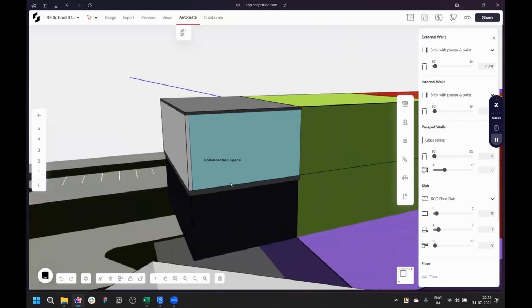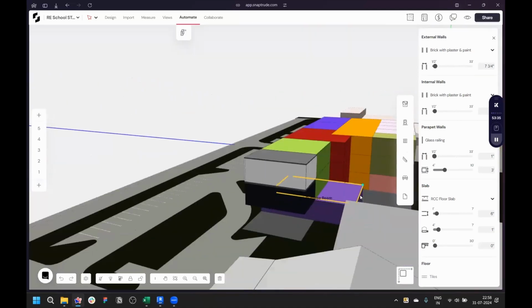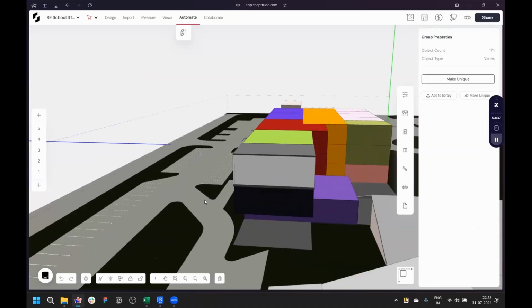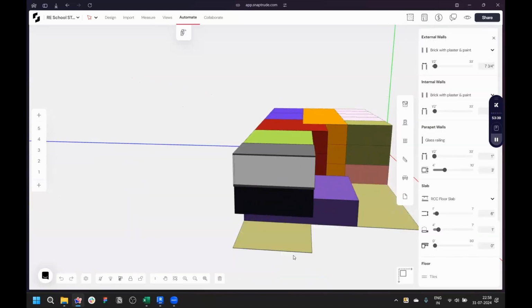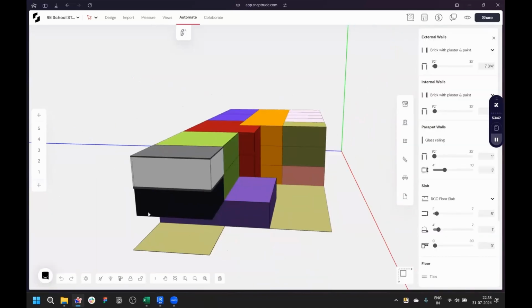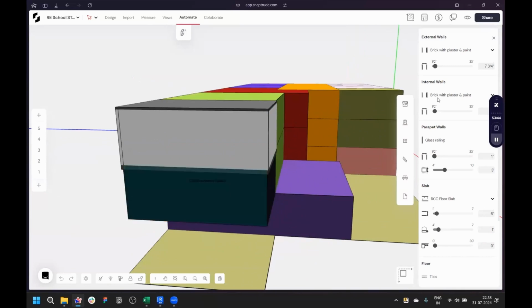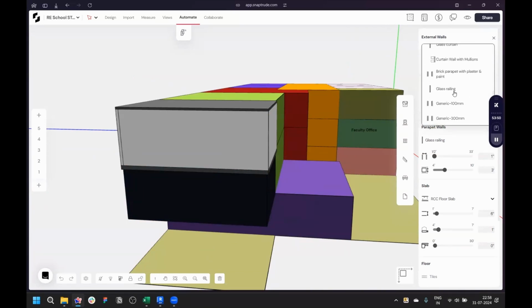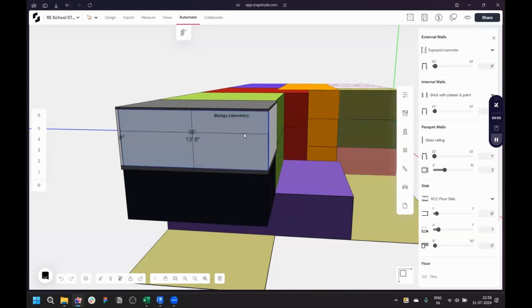And a couple of things. First of all, the person in the chat asked about exterior, what type of walls? This is what I was referring to. In our create building functionality, you can choose the type of wall, and it's actually the wall family that you can import from Revit. So if you're using Revit and you have these wall families already built, you can choose the ones you want for exterior or interior, and then you can modify them. And I'm sure Archit will show that to you in a minute, but you can modify them wall by wall, or with a select all like type functionality.